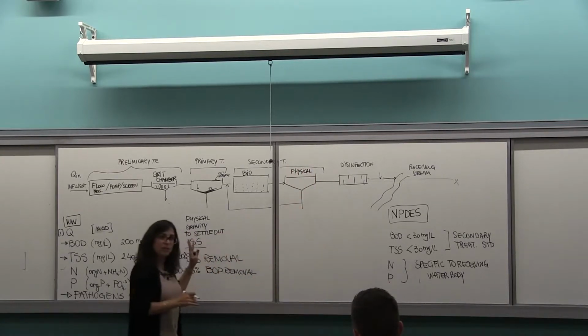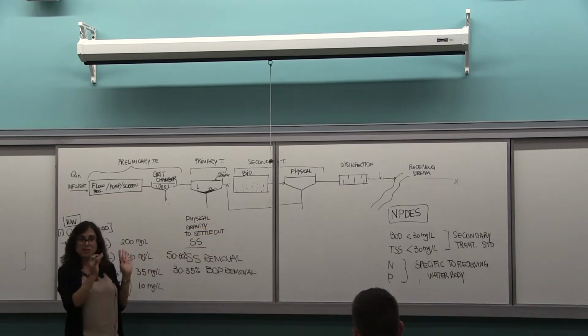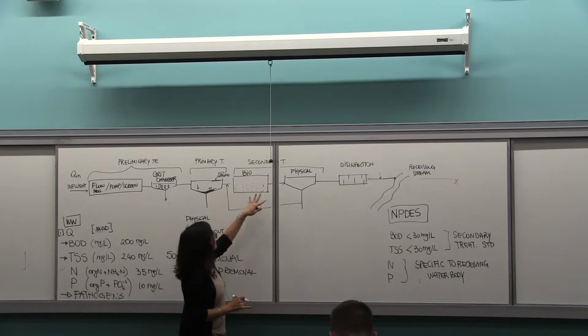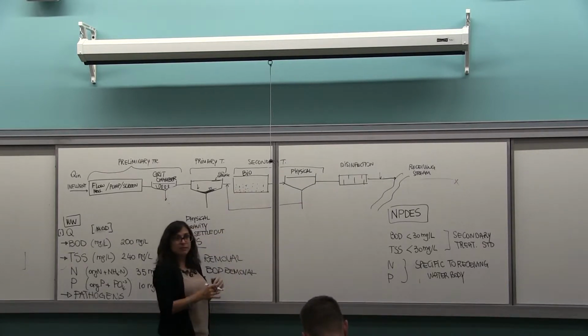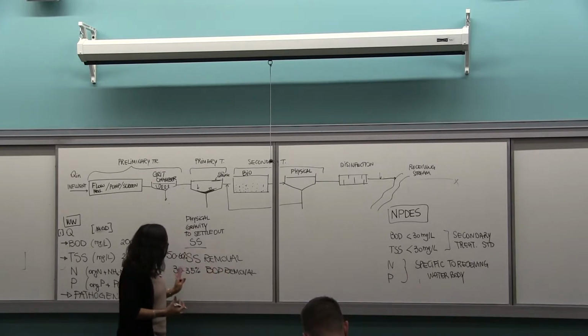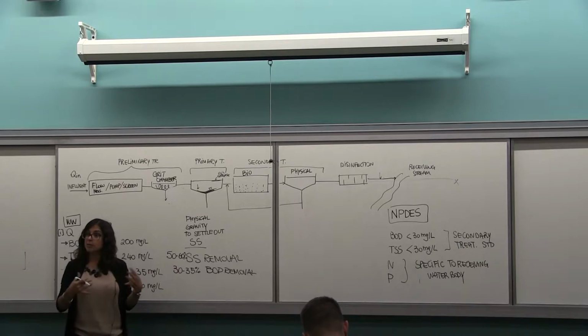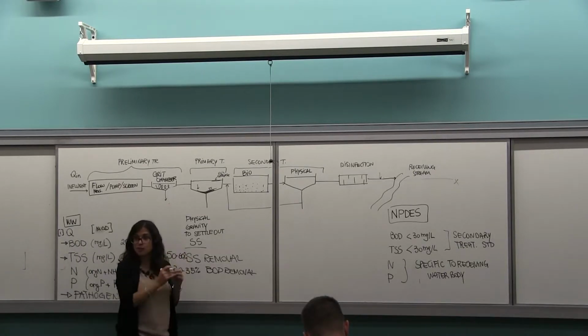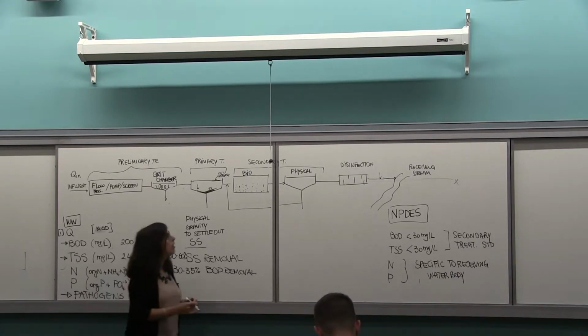We're going to be doing a problem on this part, so we'll go back a little bit. How does it work? But essentially, you have air that is added. Air, you have food, that is the BOD. You have the workers, that are the bugs, and the process, that's accelerated degradation of organic in a confined space.